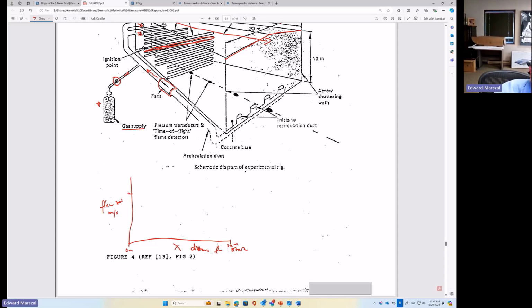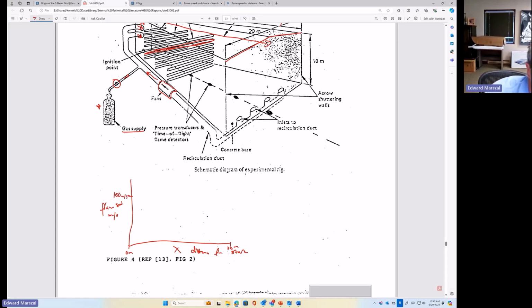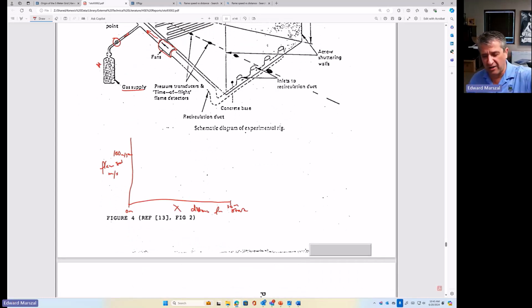And the number that we're worried about is going to be about 100 meters per second. I have a much better graph somewhere else that I was not able to locate, but I'll try to piece through the figures in the rest of the report to show you something. For just one study, what you're going to see is that the flame speed is relatively steady, and then the flame speed will take off exponentially. Here, I'm going to draw a line at this inflection point.